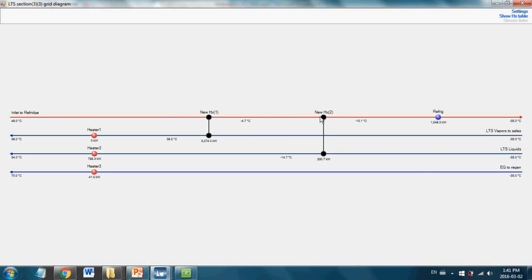We can extract some of that heat to heat up the low temperature liquids. So I put it in series with that first heat exchanger, and I can then provide 330 kilowatts of heating to this. But I look at that and I say, well, there's still heat available in that stream. Obviously I still need to cool it down using 1.5 megawatts of cooling. So there's still heat available.